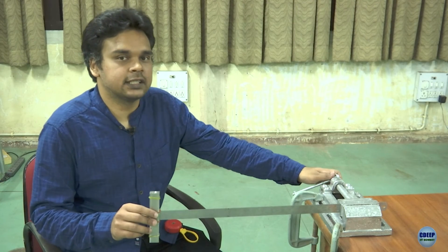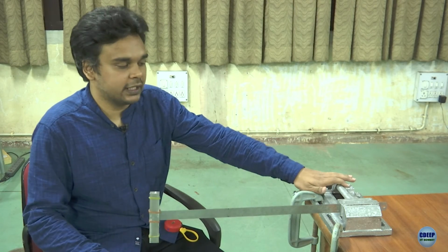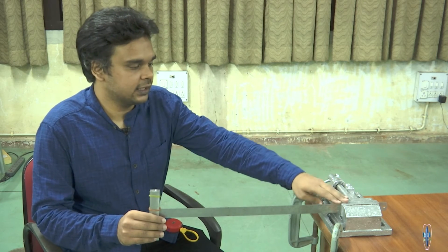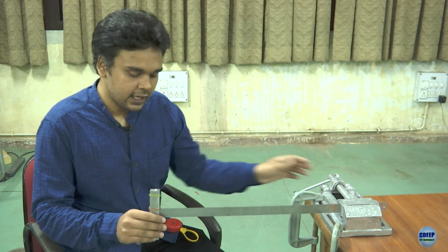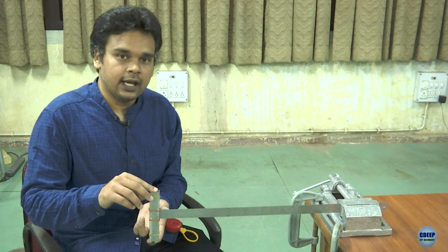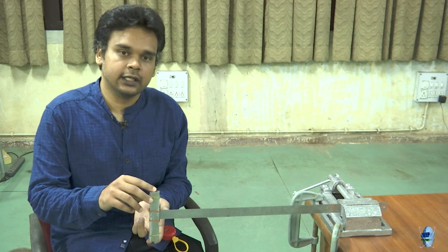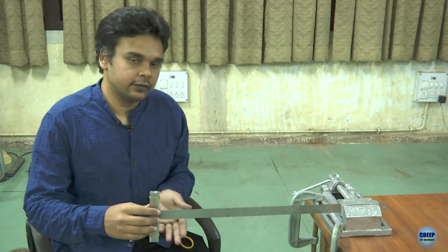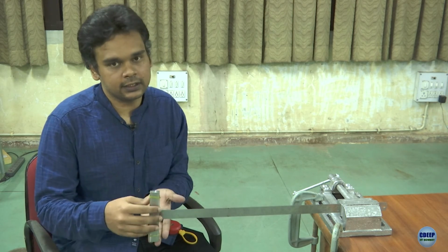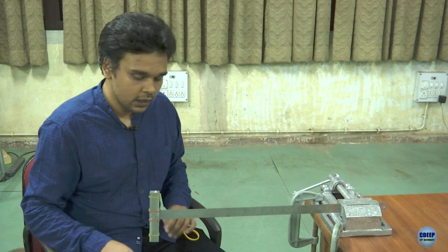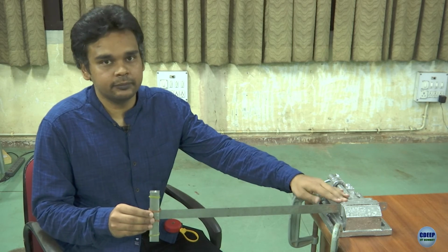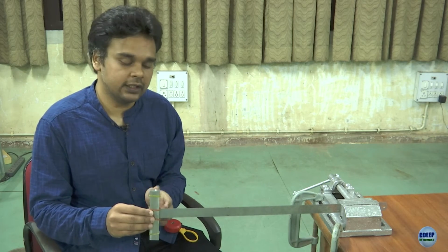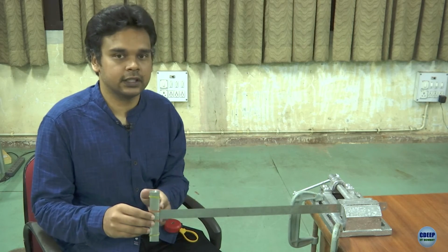So, this is the experimental setup for a cantilever beam. We have used a bench vice to set up the elastic steel scale as a cantilever beam, fixing the scale at one end using a bench vice, and we have attached a mass at the end, as I have explained earlier, to reduce the natural frequency of the steel scale, which has a very high frequency without attaching the mass. So, the effective length of this cantilever beam is from the fixed end over here to the middle of the weight.